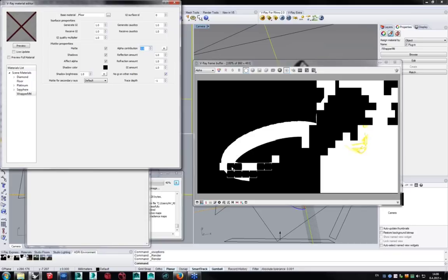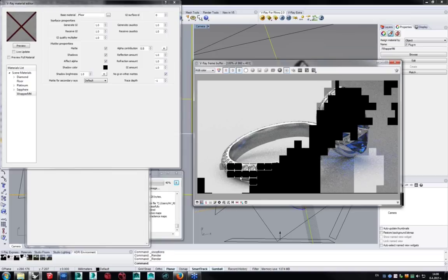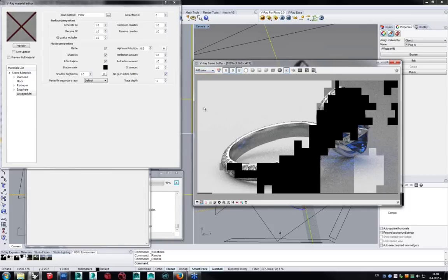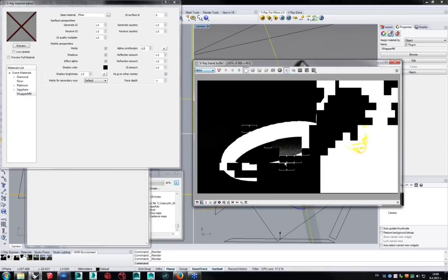But there is still one thing that we need to resolve, and this is the shadows. As you can see, there are no shadows. I'm casting lots of shadows, but none of them are in my alpha. So let's stop that, and let's put that to -1. So -1 basically means that it should catch the shadows that I just told it to. So again, switch to my alpha, and there we go.